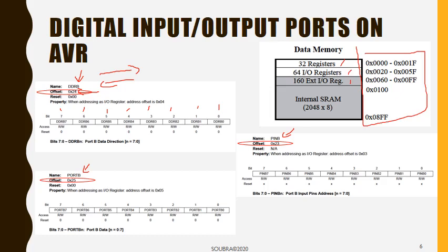So an offset is what allows you to reach one particular register, and this is done by using a base. So if we go with the base 0 here, our register DDRB is reachable with an offset of 24. So 0 plus 24, it should be somewhere around here. So we can notice that it is an IO register, and it's not a general purpose one.